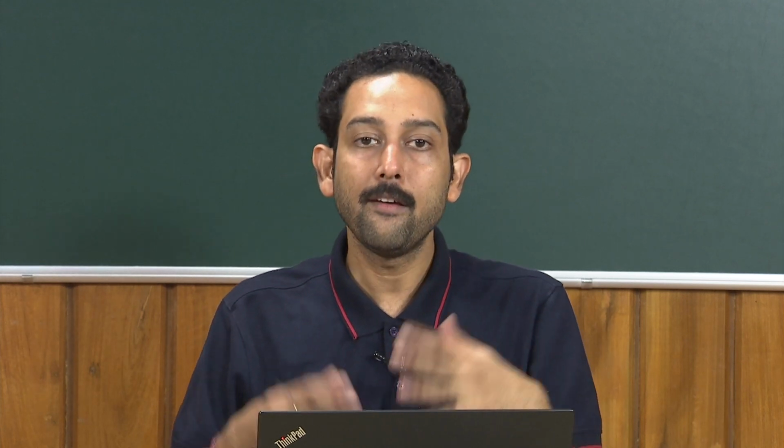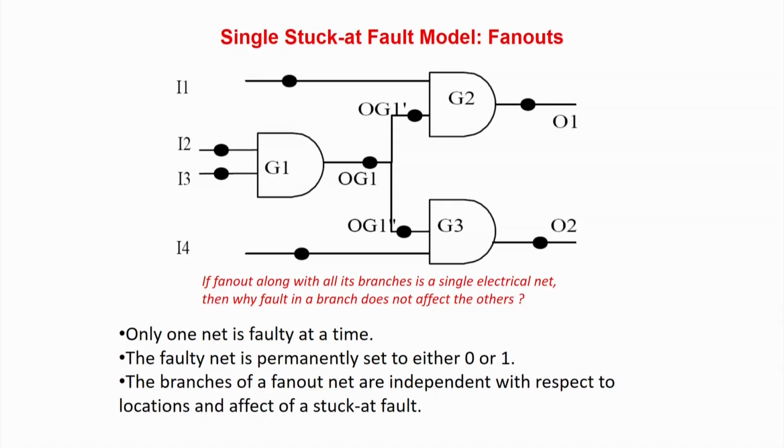So, the fault model was a phenomenal discovery. It is statistically shown that if you verify on the basis of a fault model, mainly the stuck-at fault model, there is a very high probability, 99.9%, that the circuit does not have any functional defects. Some people have modified the fault model for fanout, but I am just showing you the stuck-at fault model.